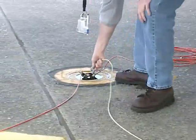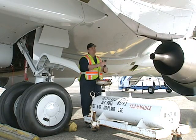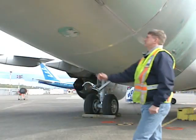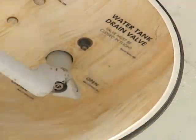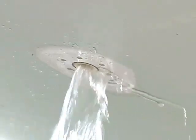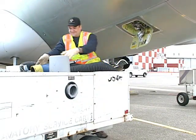Remove as much fuel as possible by pumping out to a fuel truck. Now make sure the airplane is leveled to the specifications for defuel provided in the maintenance manual. Note that the pitch of the aircraft may not be 0 degrees. Then attach fuel drains to the sub-drain fittings. Allow the fuel to drain until there is less than 1 drip per second.